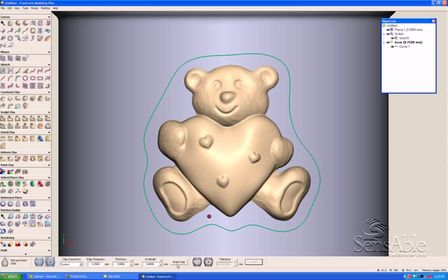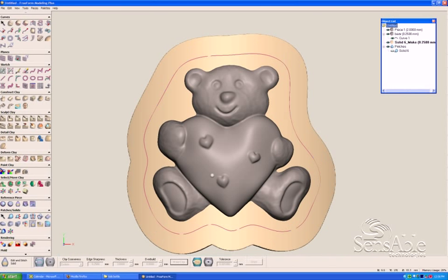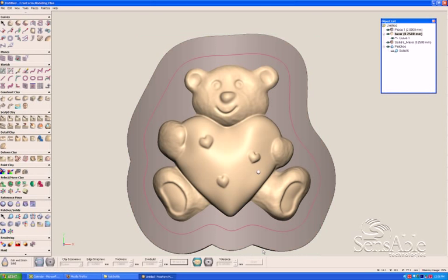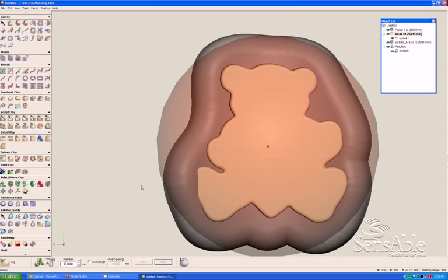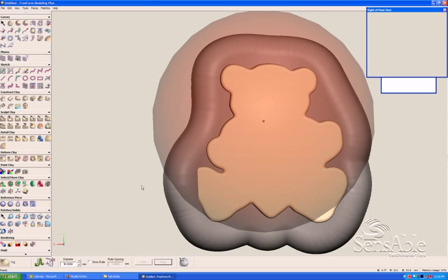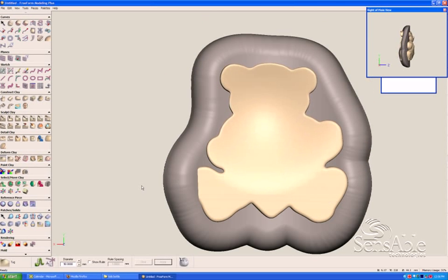So what I'm doing now is I'm creating a trim line for this model, and I'm going to delete the inside of this surface on the baby's bottle and thicken it with an overbuild to a voxel geometry. The reason we've thickened it with an overbuild is so that we have a substantial amount of geometry with an overlap, so that when we do create a surface, we have some overlap to trim and then stitch the surfaces into the model of the baby's bottle.